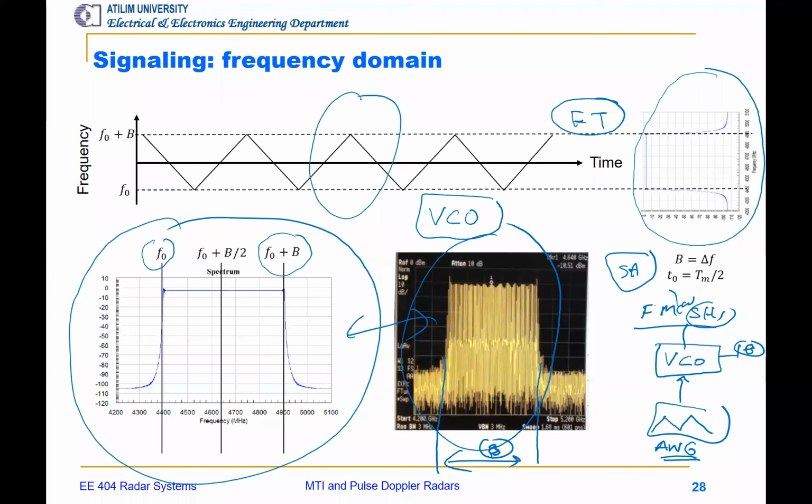Let's say you two. If I look at you from that way, I will see two echo signals. But in order to discriminate these two echo signals, the range resolution should be half of that, C tau over 2, right? So it's going to be C over 2B in here, so the bandwidth. So I have to choose the bandwidth here such that the distance between you should be measured, okay?